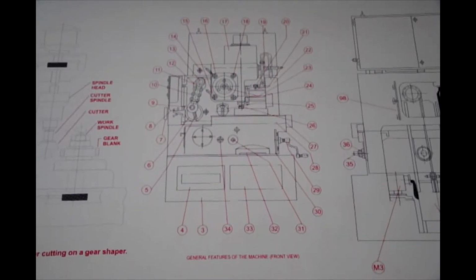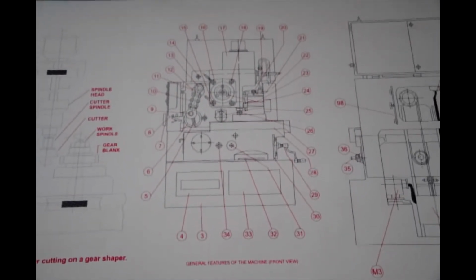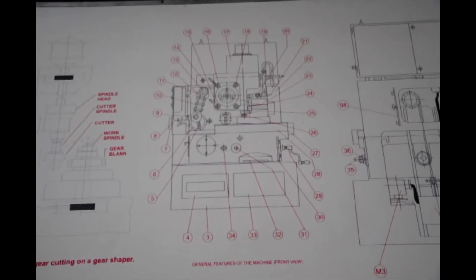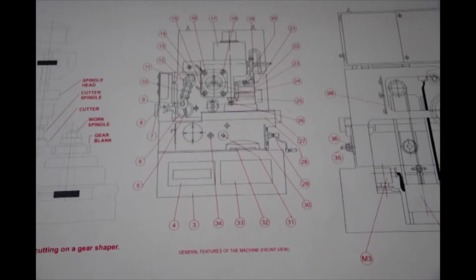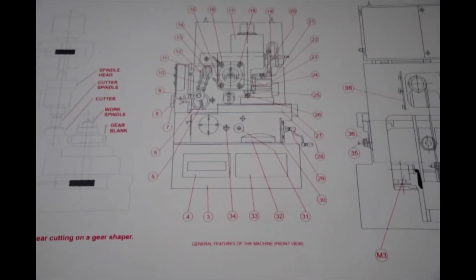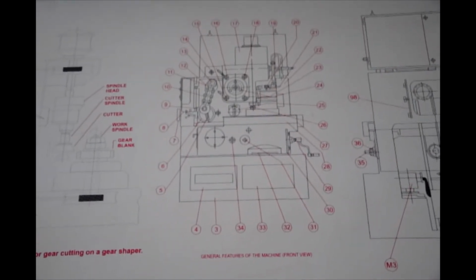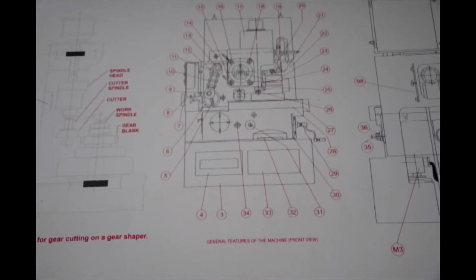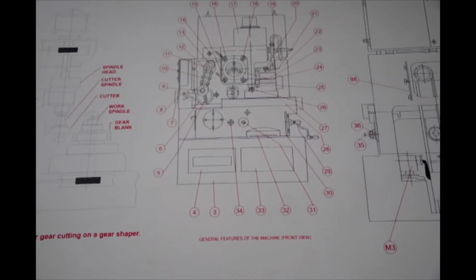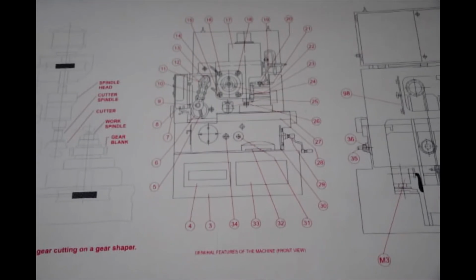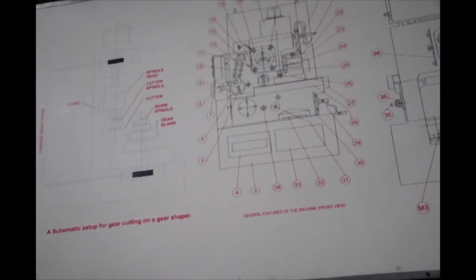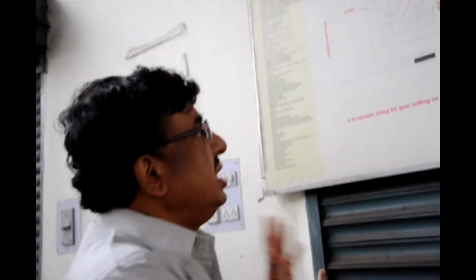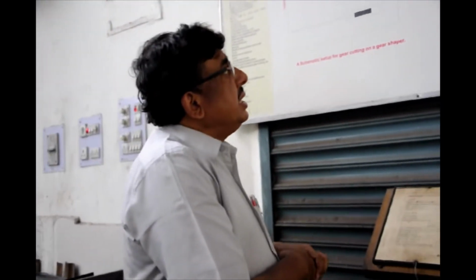The difference between the gear hobber and the gear shaper is that in the shaper the axis of the cutter and the axis of the workpiece are parallel, whereas in the gear hobbing machine it is perpendicular to that. A gear hobbing machine can generate a better tip profile, but a gear shaping machine gives higher productivity and also internal gear cutting. But a gear hobbing machine can also produce spline shafts, which the conventional gear shapers cannot produce.